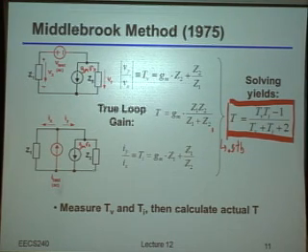That is true, although that one's also a little bit tricky. Because, for example, if I have a very high gain structure, the errors you're looking for may be very small in the closed loop. And so it may be hard to tell from the closed loop response how much of an error you had in the open loop response. That's not a bad solution, by the way, but there's another even simpler thing that you can do.